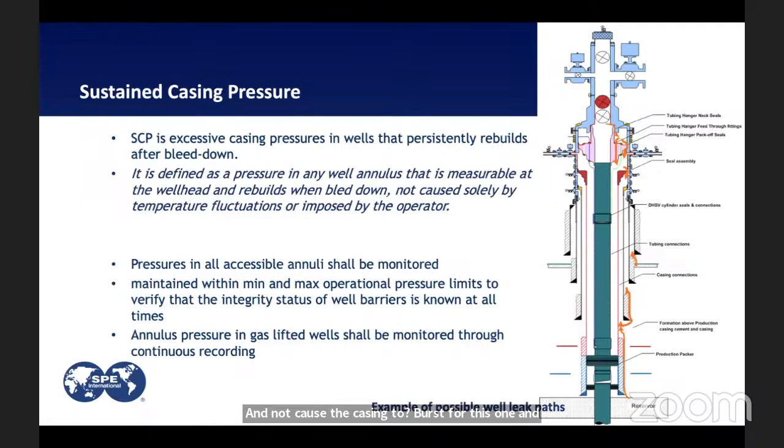Actually, it's not for all situations. For onshore or for the wellhead towers where we have dry trees, the cement could be way above, but it is not mandatory for all the casings to bring cement to the surface. Is it okay?